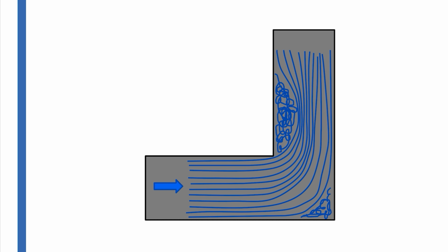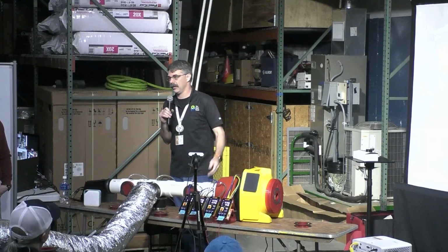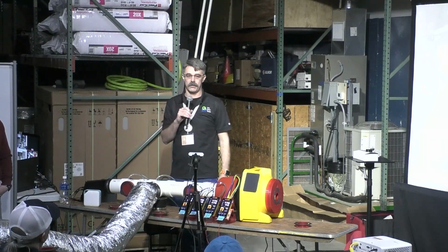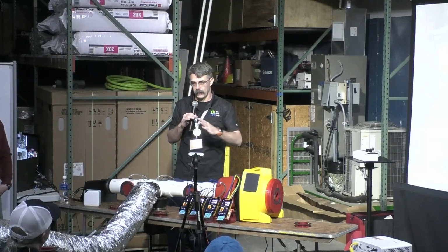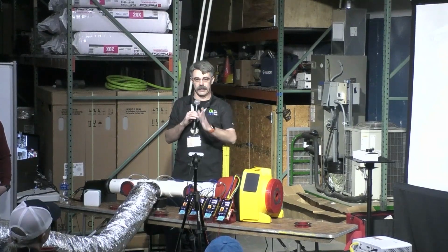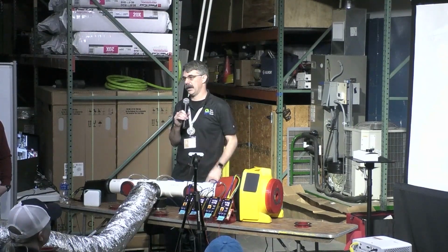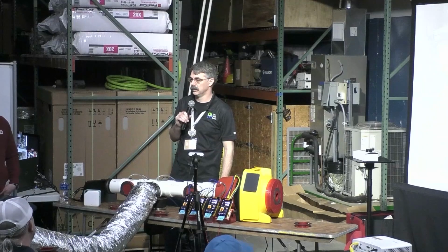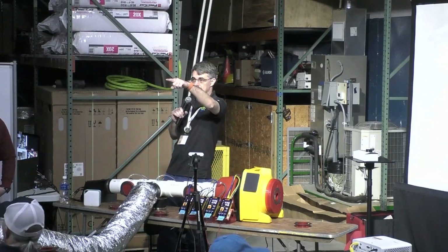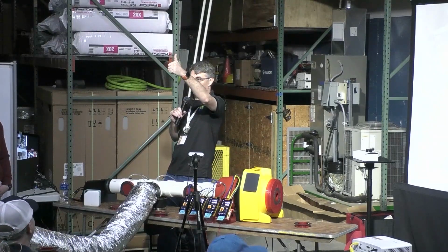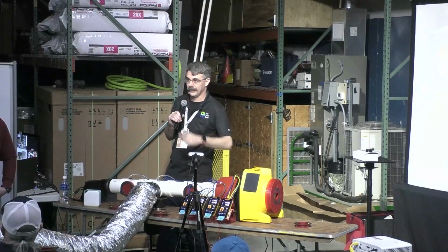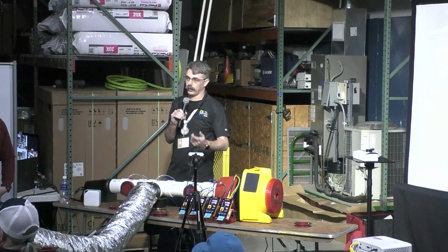Whereas if we had made that bigger, we lower the velocity going around that corner, and everybody gets to make the turn, and we don't have spinouts and wrecks and crashes on the sides. Did that answer the question? Okay, bigger ducts, more free area. Thank you. And if they sweat, make them smaller.